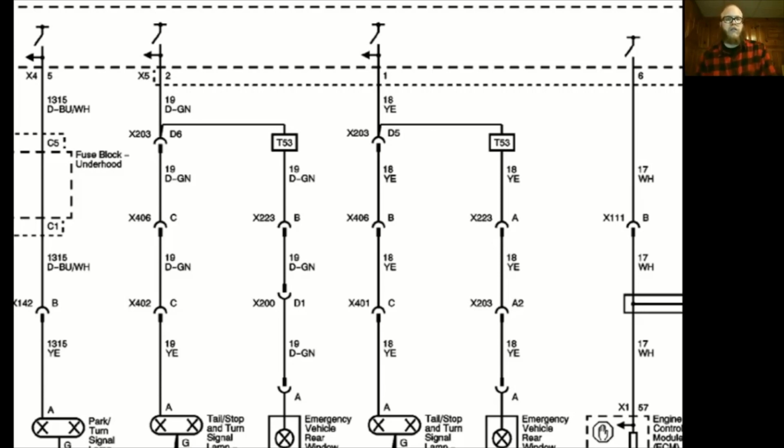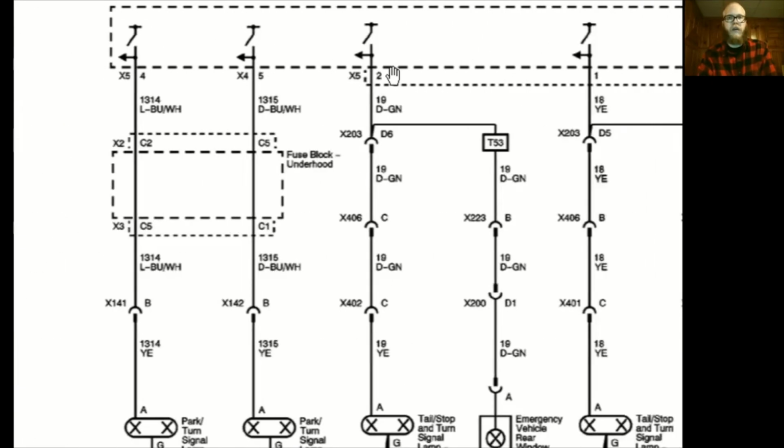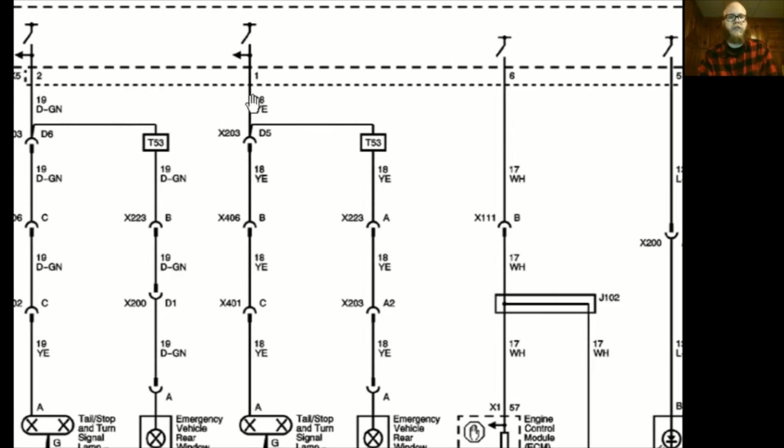It's going to then try to output to my stop lamps, and it sees that this stop lamp here on pin 1 of the connector going into the body control module, sorry to move you around so much, doesn't change state from 0 to 12 or 14 depending on how this is controlled, and it can actually set either a code or maybe the dummy light on the dashboard comes up and says that you have a taillight out, because it's kind of hard to tell if you have a taillight out because you're not really looking that way. So this is how the computer can monitor itself. This is how codes can be generated. And we're going to get into that kind of stuff next week, which I hope you're excited for.